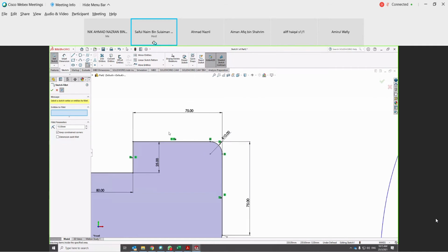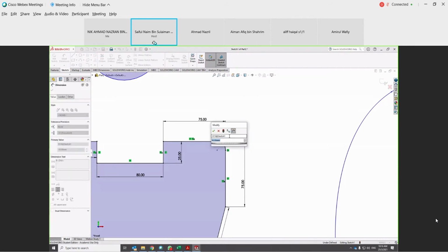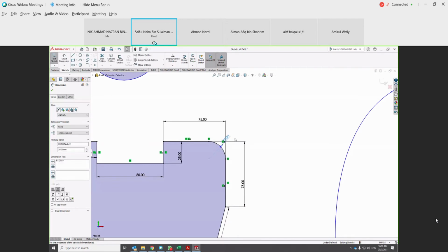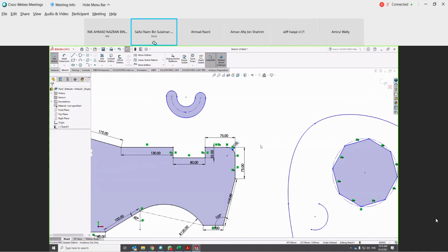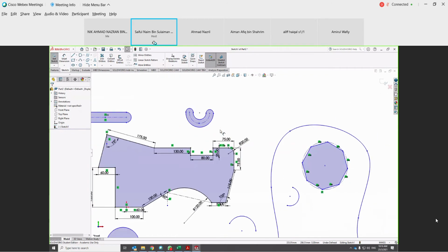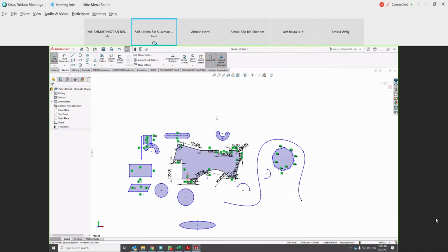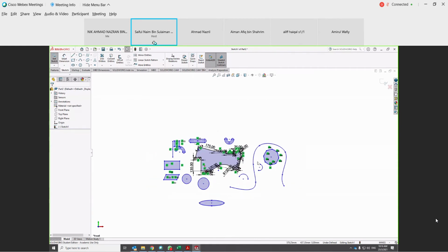Kalau you buat dalam drawing, contohnya kalau you edit the fillet punya size, so this will also affect other drawing punya relation lah, boleh effect. So biasanya kita buat fillet ni pada 3D model unless you memang betul-betul dah confirm dengan fillet punya size and so on lah. Okay, so these are all other functions of sketch.